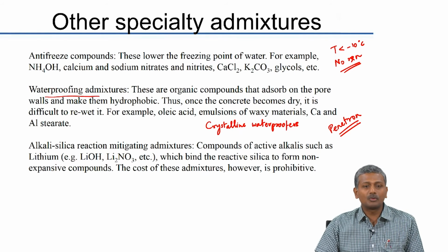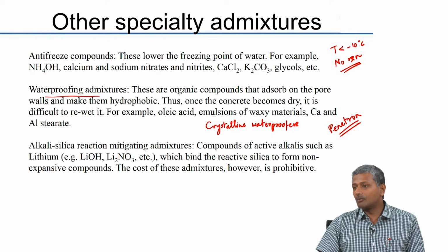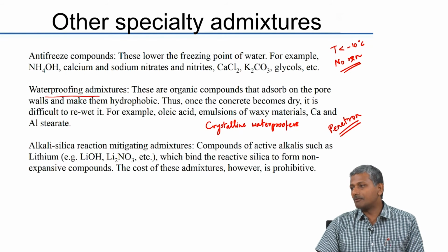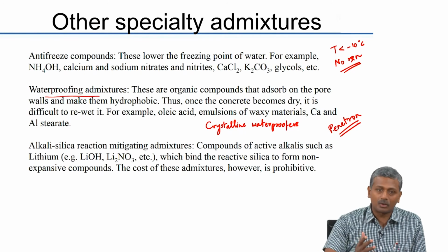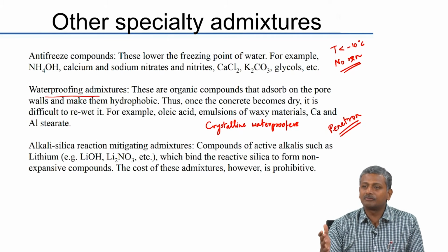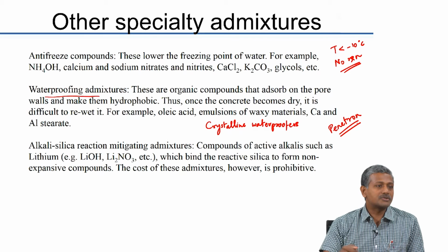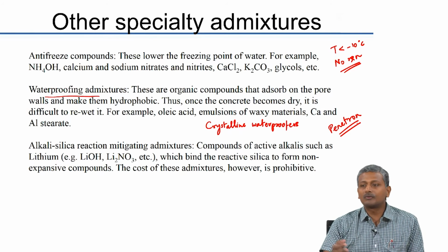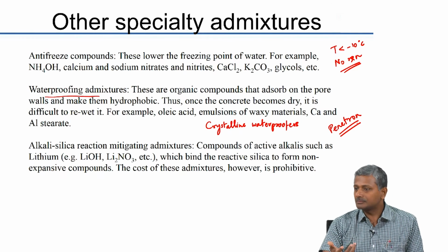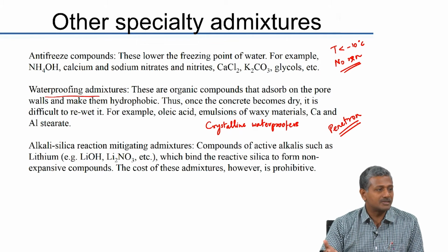The problem there is, the utility tunnel is carrying a lot of electric cables and things like that. If a lot of water gets in, then you obviously have a problem. So, water was actually seeping in through the concrete also. Why was it seeping in through the concrete? Because there was no other alternative for the water to flow, which was provided in this tunnel, because they thought it was a waterproof concrete, water was simply not coming through the concrete. But obviously you can't stop the flow of water, it will try to find a path wherever there is weakness.